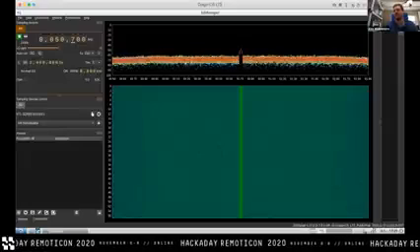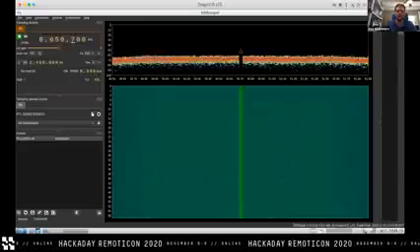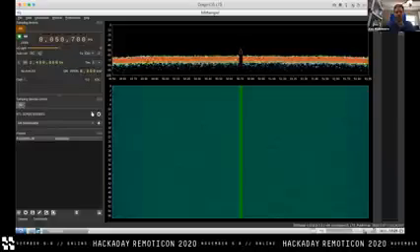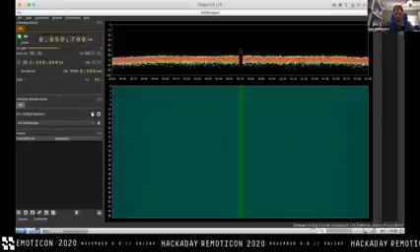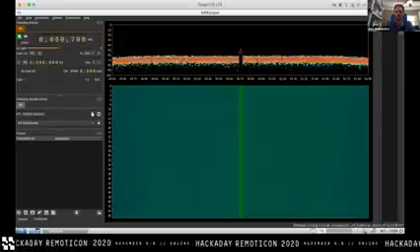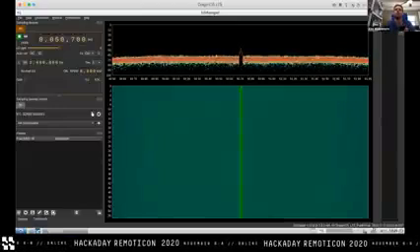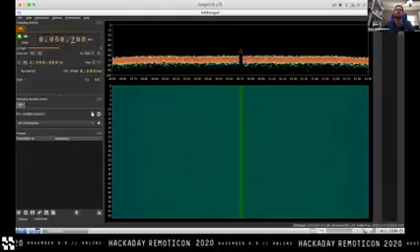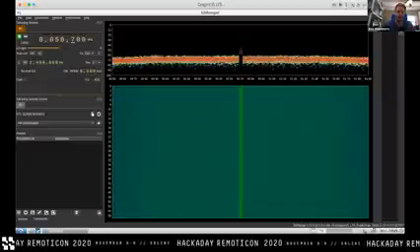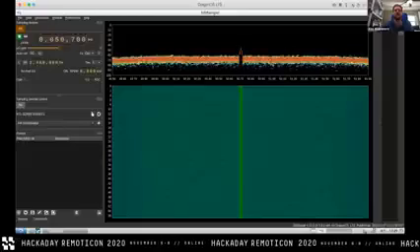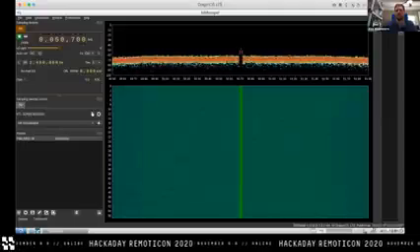So for this RTL SDR, the real-time bandwidth is 2.4 megahertz, and the total tuning range is, what, 24 megahertz to like 1.7 gigahertz or something like that, which means that this SDR is not useful for Bluetooth because it can't tune to 2.4 gigahertz, and it also can't tune the entire 80 megahertz of 2.4 gigahertz spectrum. So the 2.4 gigahertz we all know and love for Bluetooth Low Energy and regular Bluetooth and Wi-Fi exists between 2.400 gigahertz and 2.480 gigahertz. I'm sure it's slightly off of that. Anyway, it's 80 megahertz wide, which means that this SDR can't tune all of it at once. So it's not useful for that. And it also is too high. You can only go lower than that.